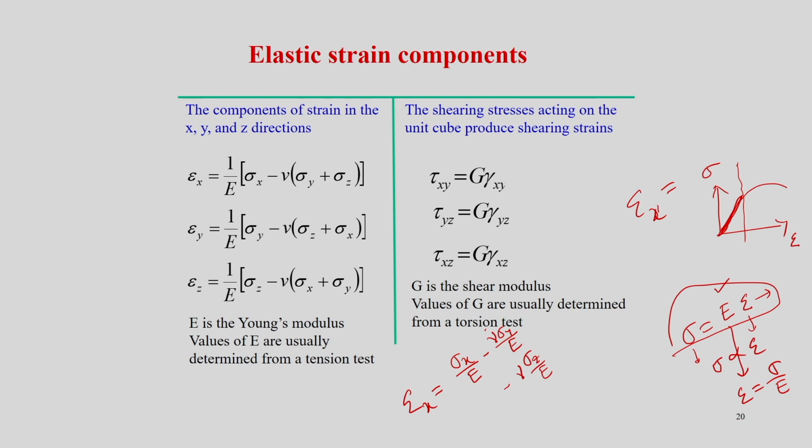Effectively it is written as: sigma x, positive, because along this direction we assume the strain is a positive value, and then we introduce the Poisson's ratio times sigma y and sigma z, minus, all divided by E. These indicate the strain because of sigma y and sigma z, acting along the normal, which takes care of the strain components along the x axis. So this is the effective strain accounting for all three stress components, modified by the Poisson's ratio.